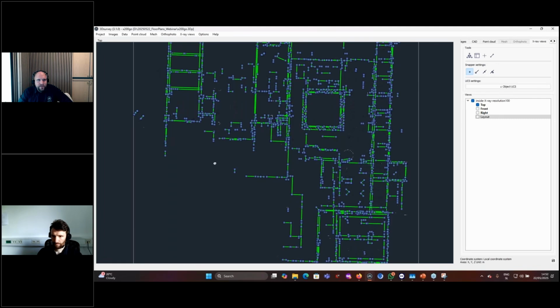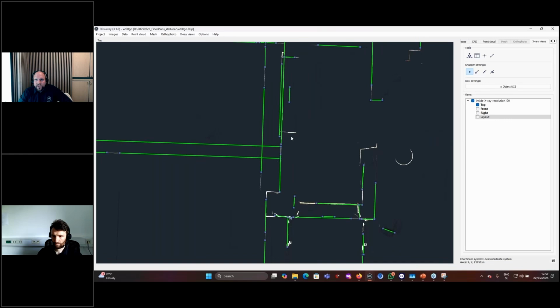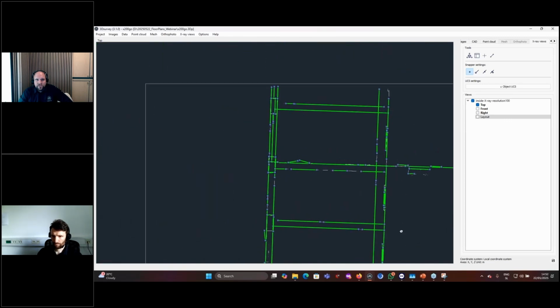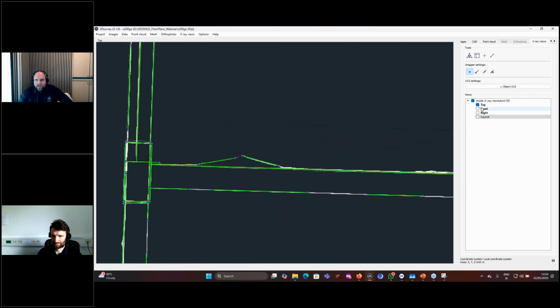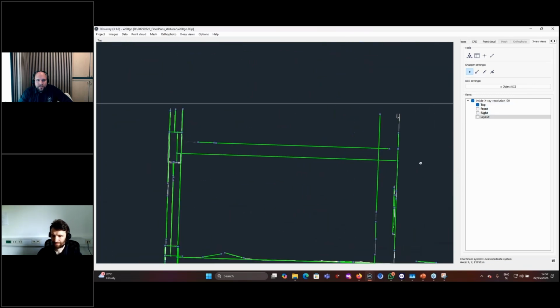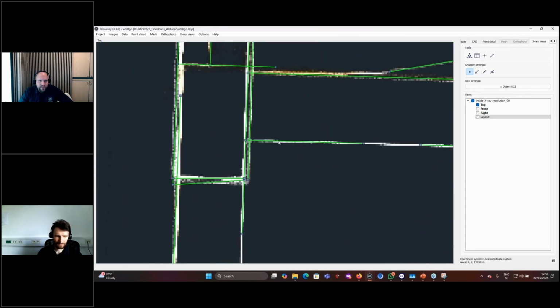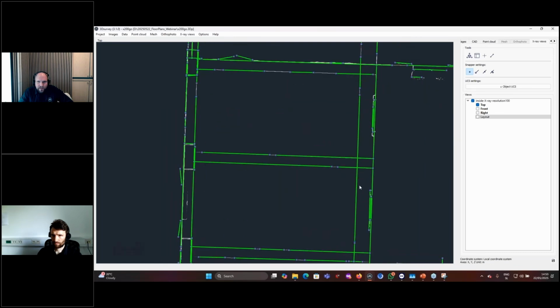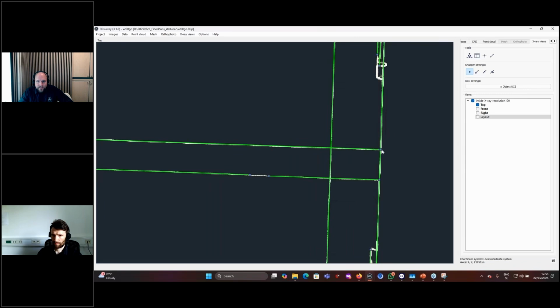Then I have this example. This is the newest one. This one is for X200 Go. So I'm not sure if this one is sorted already. Here we did automatic line detection on the whole layout, and it did a pretty good job extracting all the lines. I forgot to mention, but our line extraction algorithm usually tries to create points and vertices so that you always get snapping done automatically. So you see the vertex here is directly on our line, here the perpendicular line.